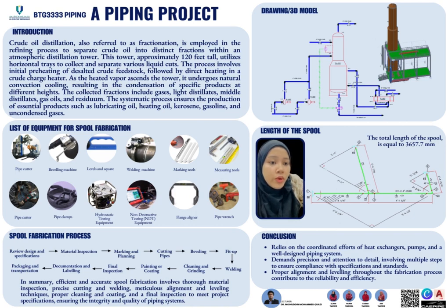It also involves the tee according to class 40, which is 105 mm, and we assume the root gap of 8 mm because it has two joints. The total length of pipe 2 is about 1995.5 mm.